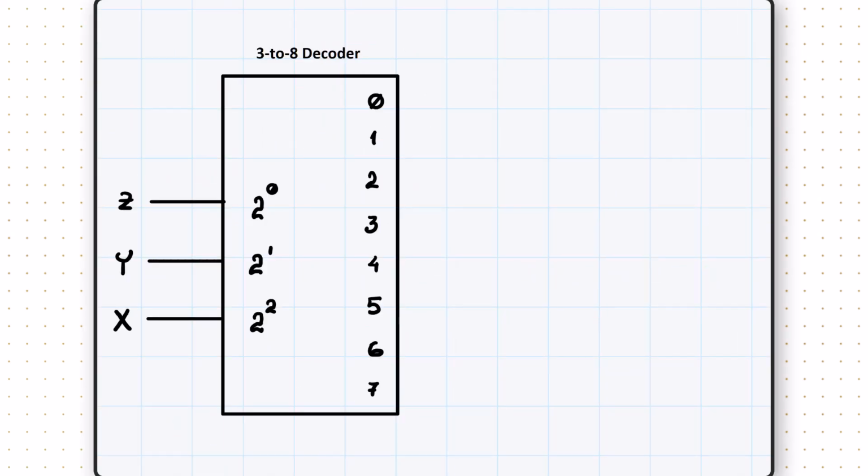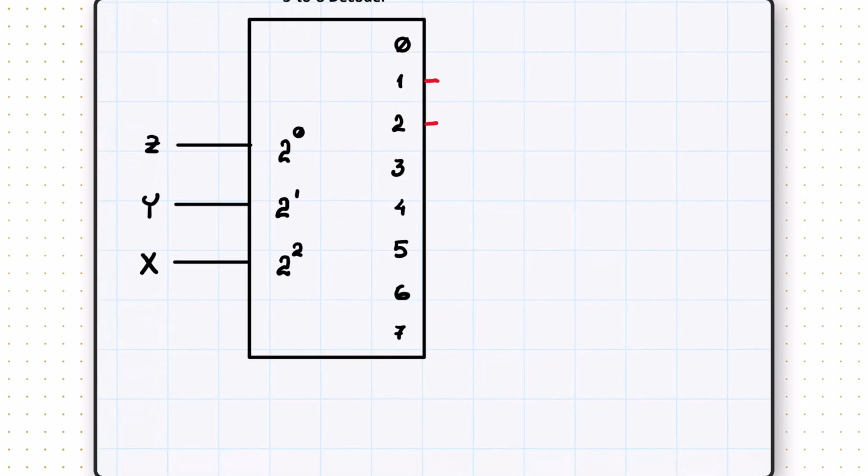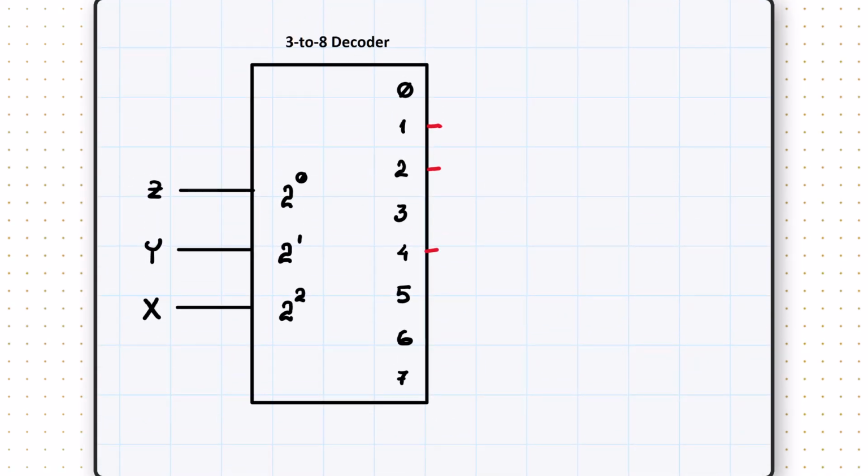Next, we'll organize all the outputs from the pins for the minterms, which are going to be combined together as inputs for an OR gate that will give us the output S. So let's do that. We are using minterm 1, minterm 2, minterm 4, and minterm 7. The ones which are going to be connected to the gate providing output of C are going to be respectively minterm 3, minterm 5, 6, and again 7.